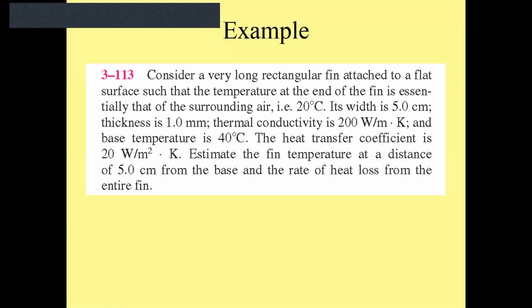Now, consider a very long rectangular fin attached to a flat surface such that the temperature at the end of the fin is essentially that of the surrounding air. By looking at this, you already know what type of case this is. If you remember from the previous video, there are 4 cases.